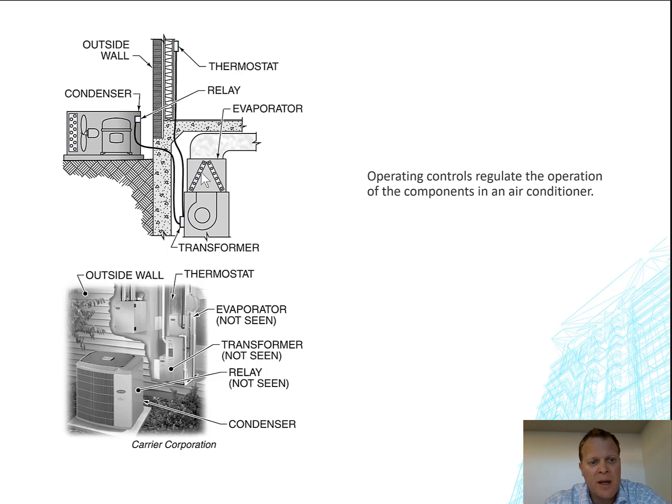And what I've seen in the past is no coordination. Even I've been guilty of it, where I assume the mechanical room is big enough. I assume we got the right dimensions on there. Well, we end up putting something pretty big in there, or oversized, or something that's got a weird configuration to it, and all of a sudden we don't have the right amount of space. So paying attention to this physical space in the mechanical room and all the lines going to and from it can be a big deal.